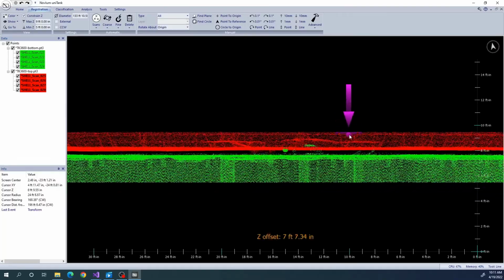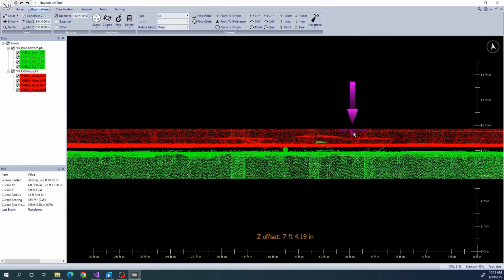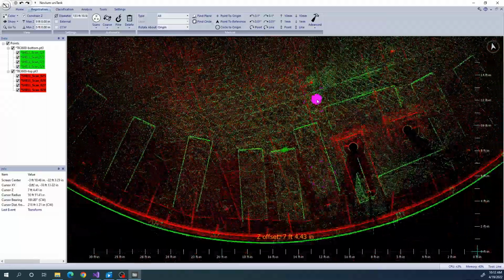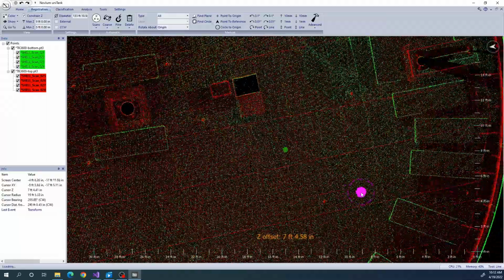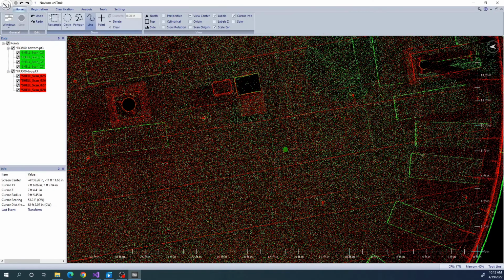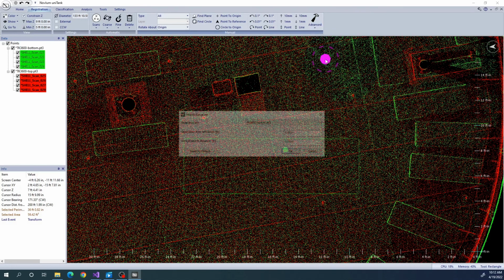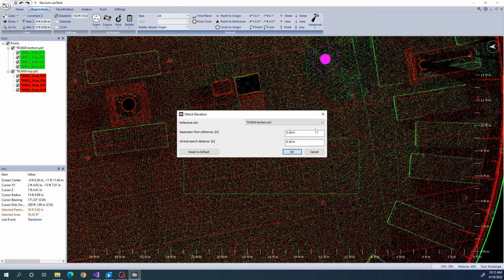Finally, we will match the elevation between the two models. We do this by selecting a common section of the floating roof and then using the Match Elevation tool. This tool will fit a plane to each model and line up the planes using the thickness of the floating roof. If you use common roof areas instead, you can use this same technique, but with a 0 thickness.